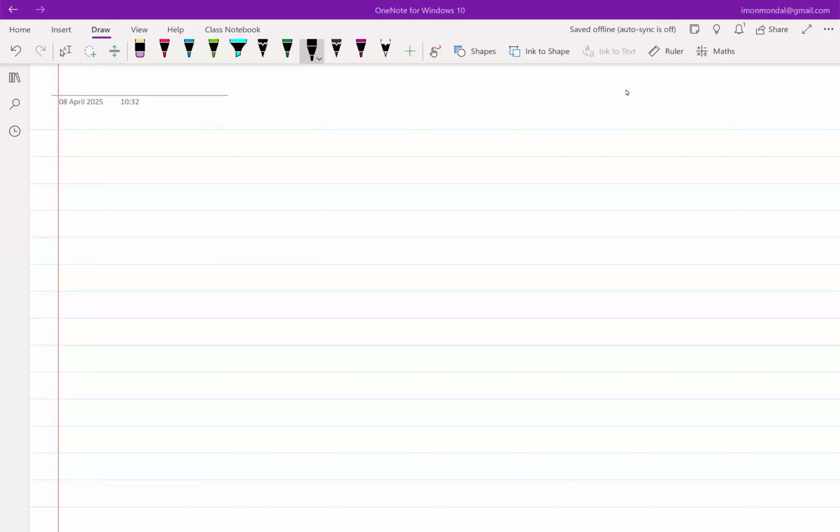The conversion gain of 30 dB is after the baseband. Yeah, so basically that translates to the baseband amplifier gain times whatever gain you get from the LNA and whatever degradation you have from the mixer, which could be equal to 30.